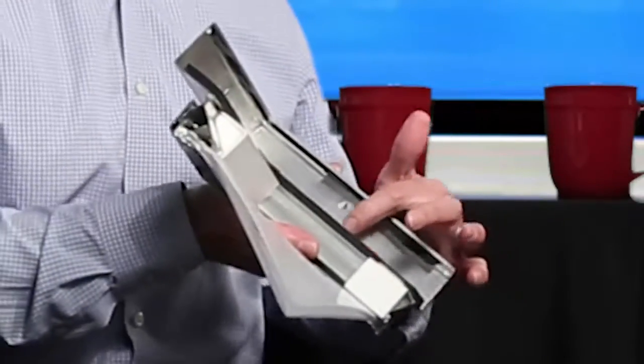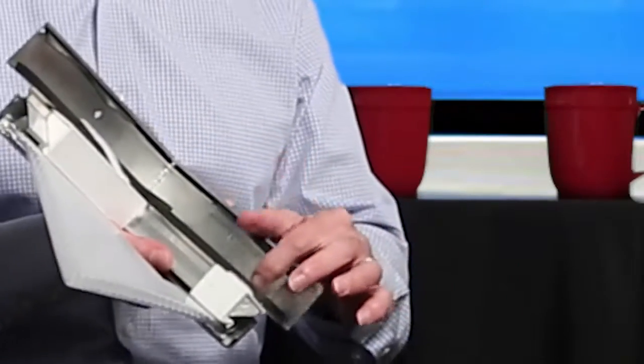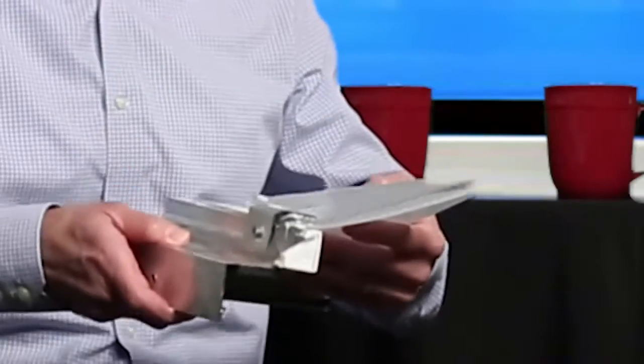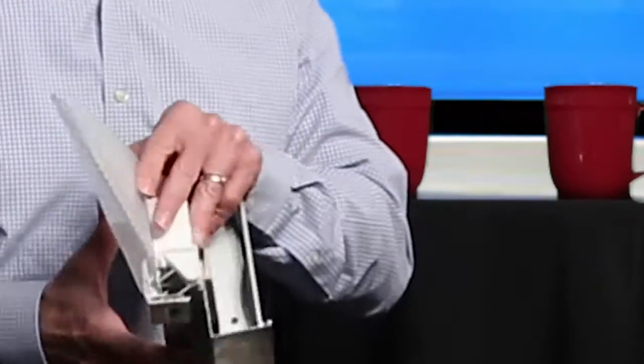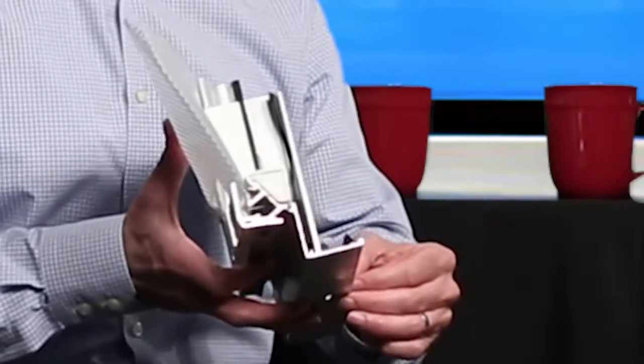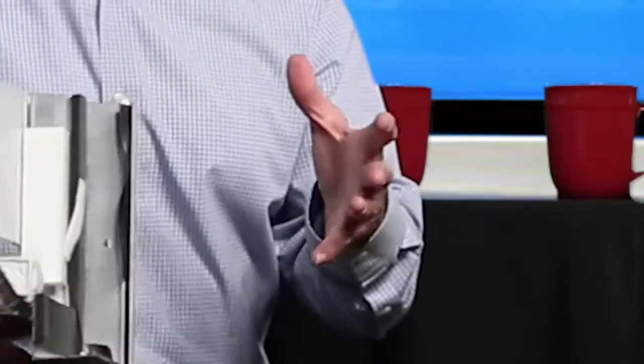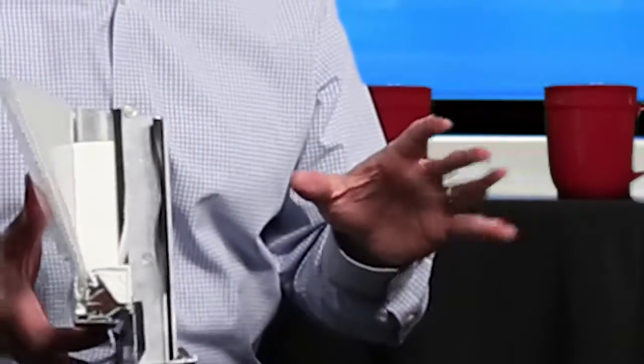The second thing we have here is this thing called a curb tape. When we use the curb tape, what that's doing is it improves the seal between the skylight and the curb as it sits down on it, which is important. We also have another quality feature called our weather sweep. What that weather sweep does is help eliminate the issue of upward rain that could maybe come into the skylight and let water into the skylight, which you don't want to have, right?